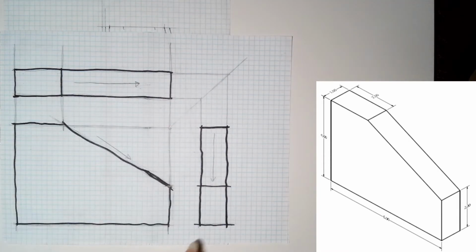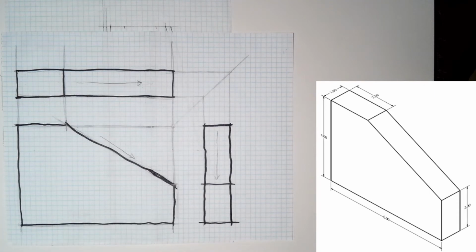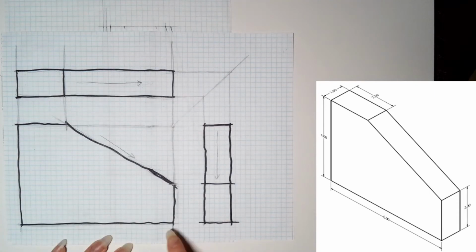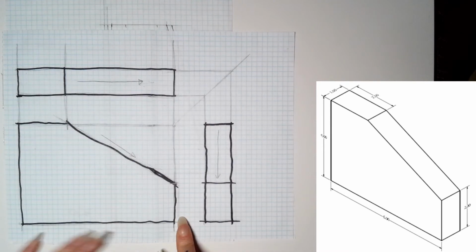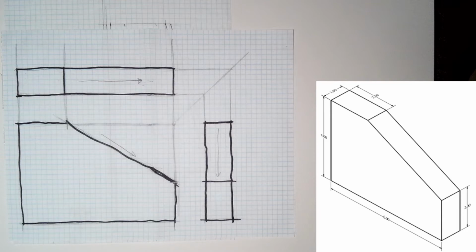I don't need to draw what the left side would look like because it's going to give me all the same information, but it would also have this face. If I'm looking at the left, I can't see it, so it would be a hidden line and it would just make things a little bit more complicated. So I don't need to draw things like the bottom, the left, or the back because it's going to give me a lot of the information I already have. So in objects like this and a lot of industrial design objects, we only have to draw the 3 views.